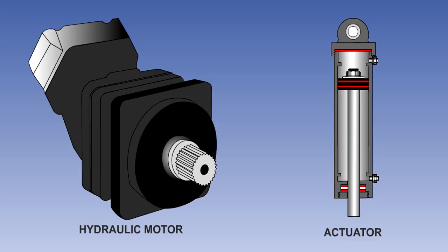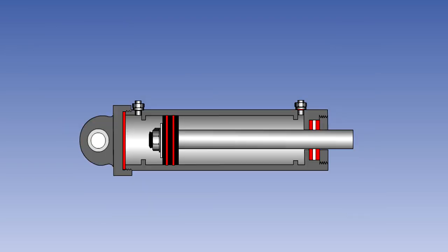In this lesson, we will examine the components that are used to convert hydraulic pressure into mechanical movement. Hydraulic actuators or jacks are used to convert fluid flow into linear or rotary motion. They vary in size and construction depending on the operating loads, but all consist of an outer cylinder within which slides a piston and seal assembly. Attached to the piston is a piston rod or ram, which passes through a seal and wiper ring assembly fitted into the end of the cylinder.